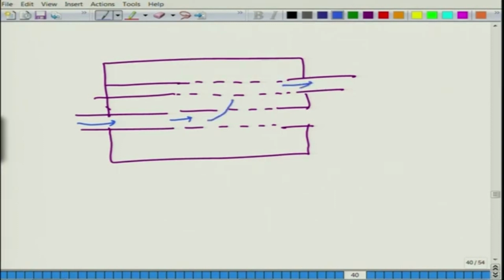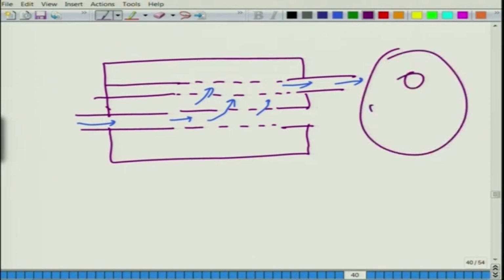So, the flow has to go through this. Okay. So, basically such an element is called a cross flow expansion chamber. Here cross expansion takes place, it is no longer a grazing flow, the flow has to go through this. So, the perforated impedance expression changes significantly. Hopefully we should be able to do that as well.